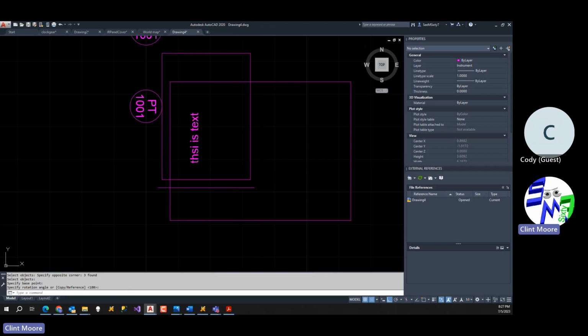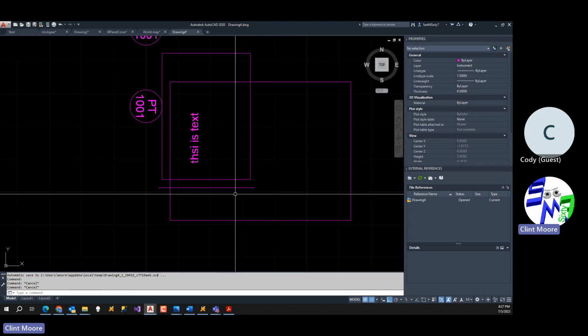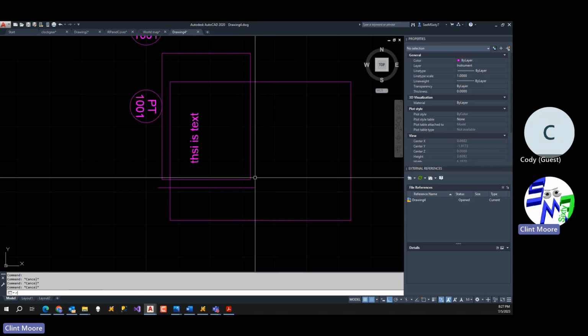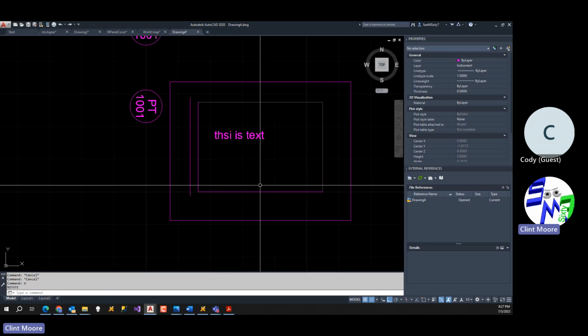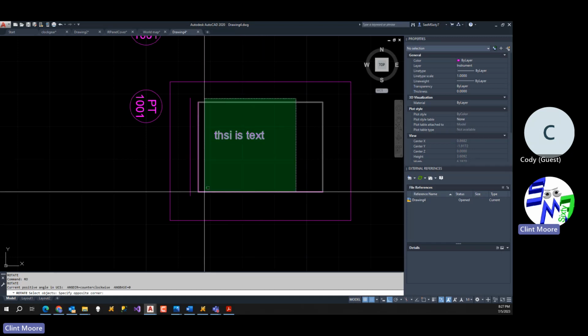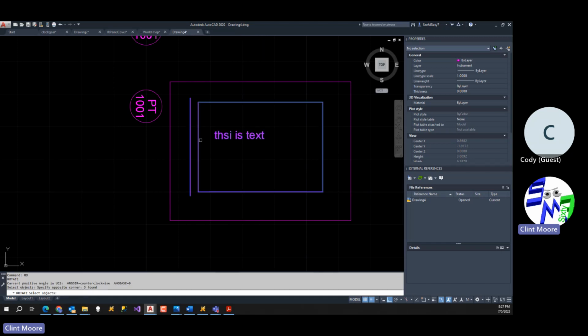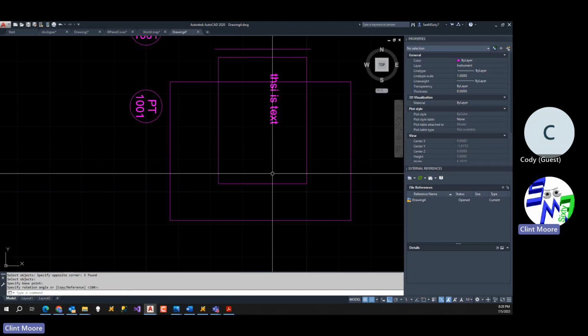So you want the text to be readable towards you. Let me undo that. You will typically rotate the plan, because this is a stick file. This is the side that everything is bound upon. You don't want to rotate that towards yourself because that's a heavy end and it'll drop down towards you and drop on your feet. So you typically rotate it down like this.